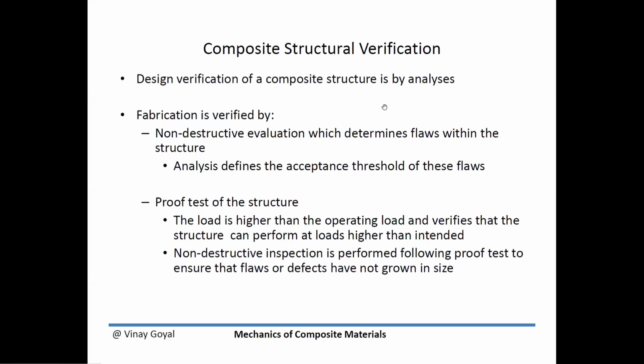So say that in flight, you may see 200 degrees F. We know the strength of the composite is decreased at 200 F, but the testing you perform on the ground is at room temperature. You can correct the proof factor and increase it over the operational loads to be able to account for the test versus in-flight differences.